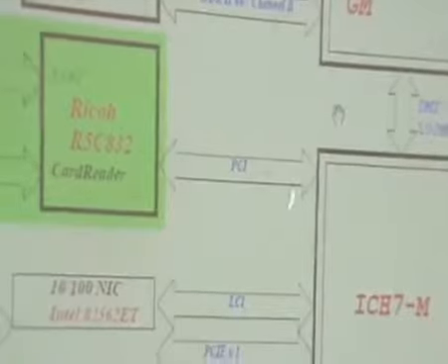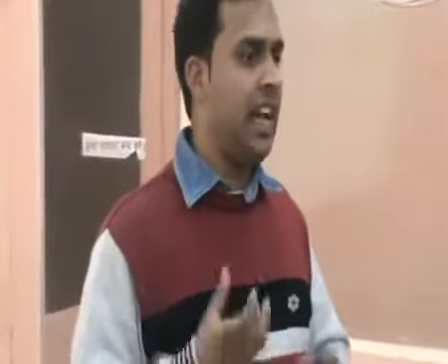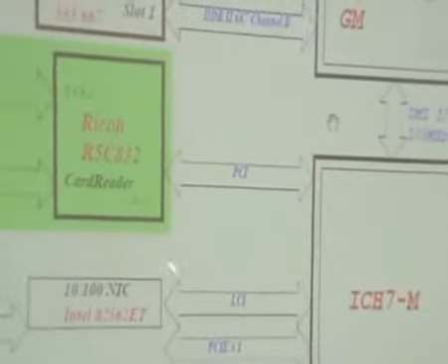That is PCI Express. PCI Express is a point-to-point connection, and PCI is a bus where you can connect many chips and they distribute. In that case the speed is distributed. At one time only one chip can work. In the PCI bus, at one time only two chips can communicate, while in PCI Express there is a dedicated connection.